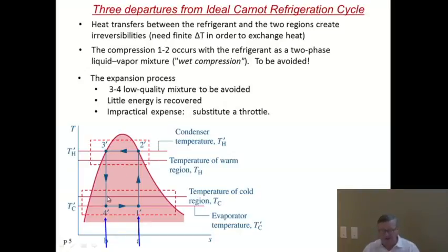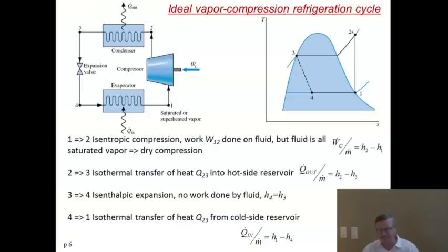You avoid it. Now, that means that the ideal coefficient of performance, which was this ideal Carnot cycle that would go between this point, this point, this point, and that point, is completely different from what is going to happen in practice, and the real efficiency is going to be less than this ideal cycle. So let's take a little look at what an actual refrigeration cycle looks like, and we'll still call it ideal because there are going to be additional losses compared to what we have here.